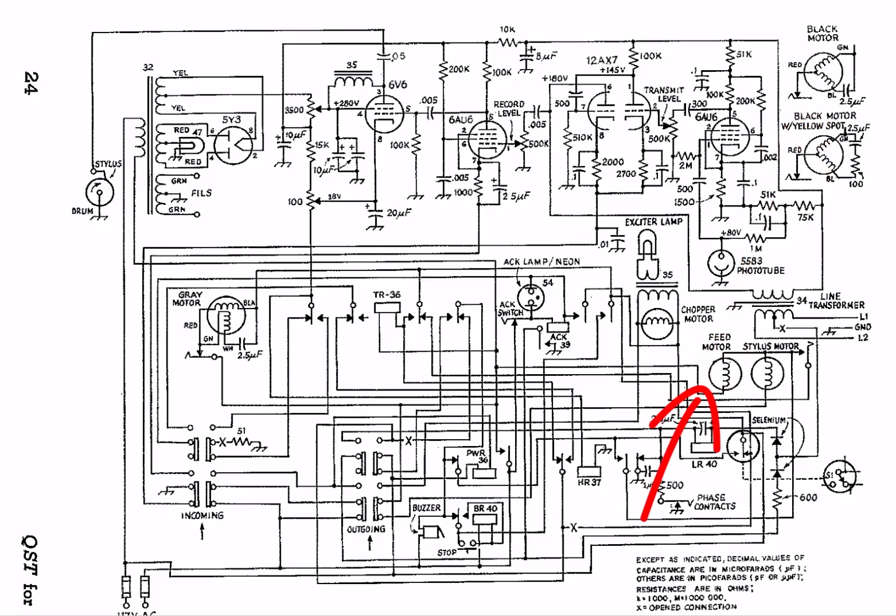Here's the carriage motor that moves the carriage under the read and print heads, the stylus motor that puts the print head tip in contact with the teledeltos paper during printing, and the chopper motor that converts the steady light beam into the 2400 Hz signal when transmitting the copy. There are various contacts and relays. Some are DC and some are line voltage AC.